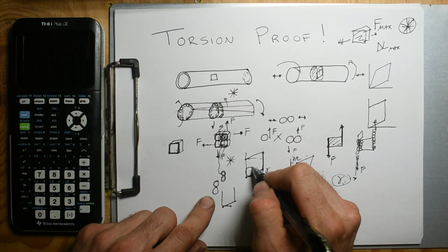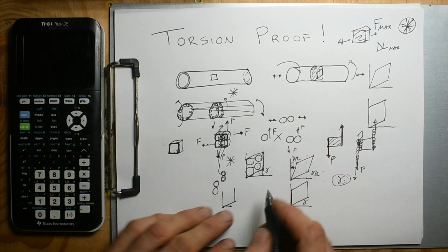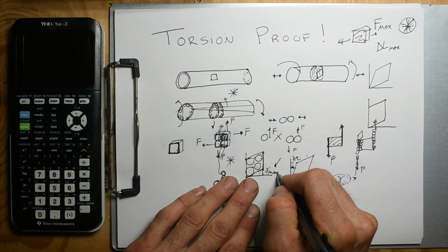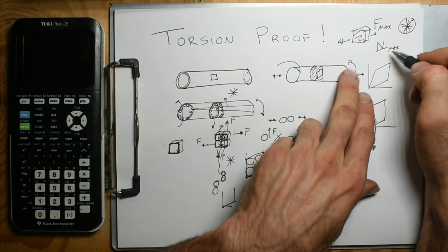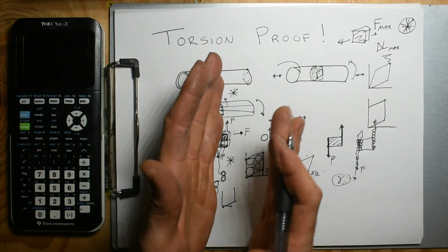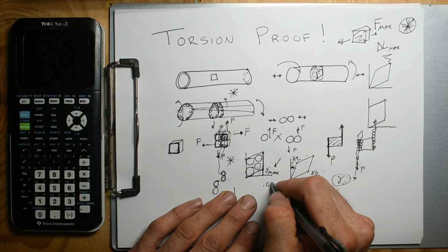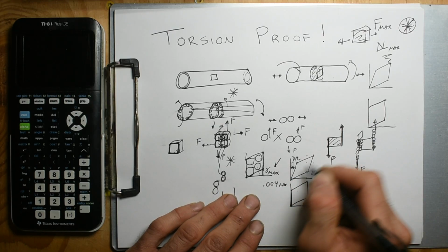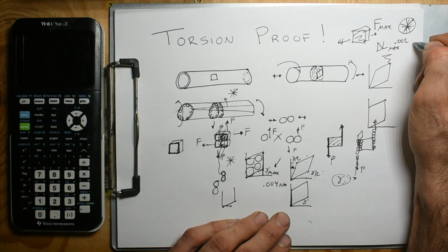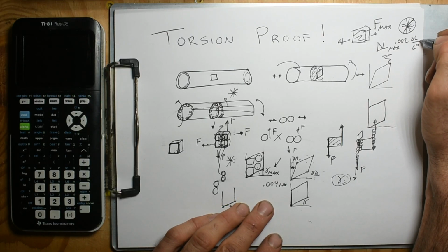They didn't break yet. And we can do this to a max. We're using this property visually. In this one, we were looking at change in length. In this one, we were looking at an angle that forms when we're doing this. And there's going to be a max angle. For steel, it's 0.004 radians. For steel, the change in length is 0.002, and this is going to be change in length per unit length.